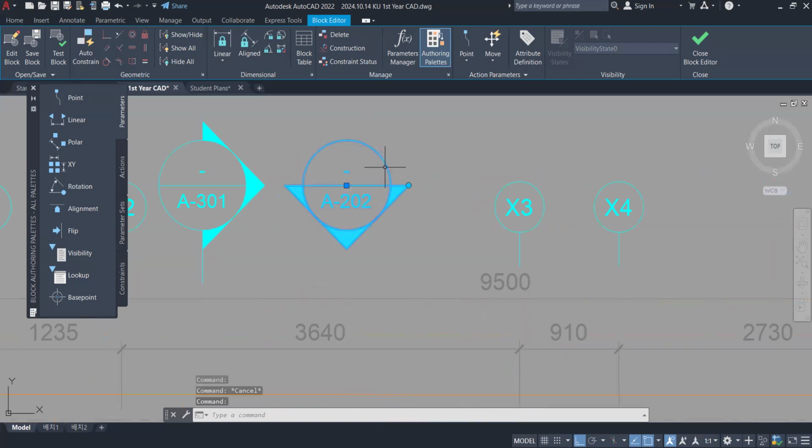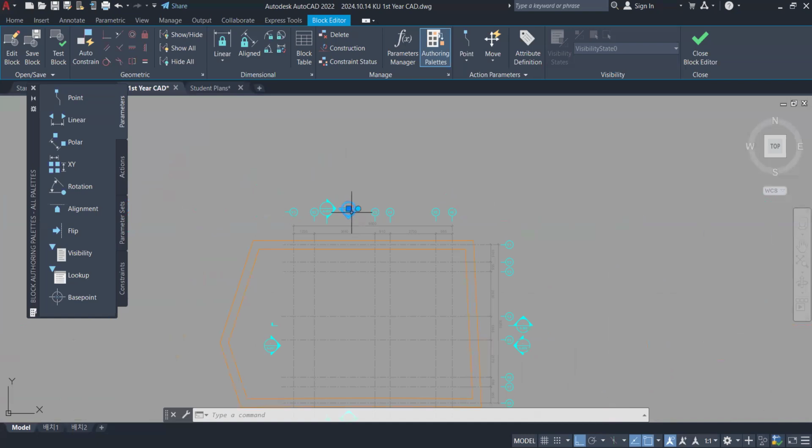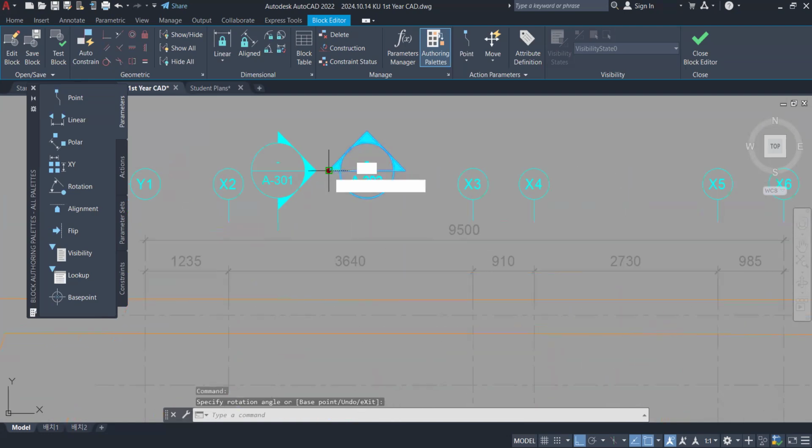You usually write the drawing number and the sheet number here. I will talk about that in a minute, but this is pointing at the east side. So east elevation is A202. And to make the other, for example, if I wanted the west elevation marker, I would pull this, and it will rotate to make all the other directions.